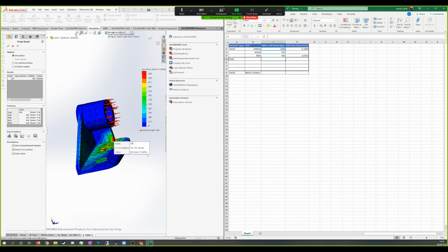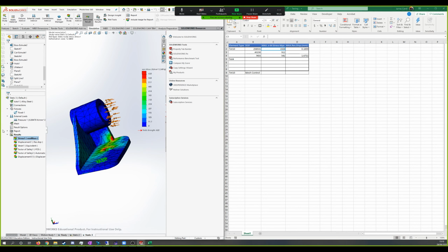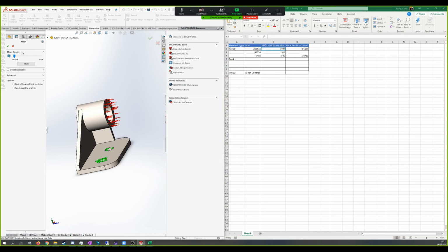So make your mesh size smaller than fine. So if you actually go recreate your mesh, click mesh parameters, and that top value, yep, that's your actual global mesh size. So when you change that slider, you're actually changing that value. Yeah.